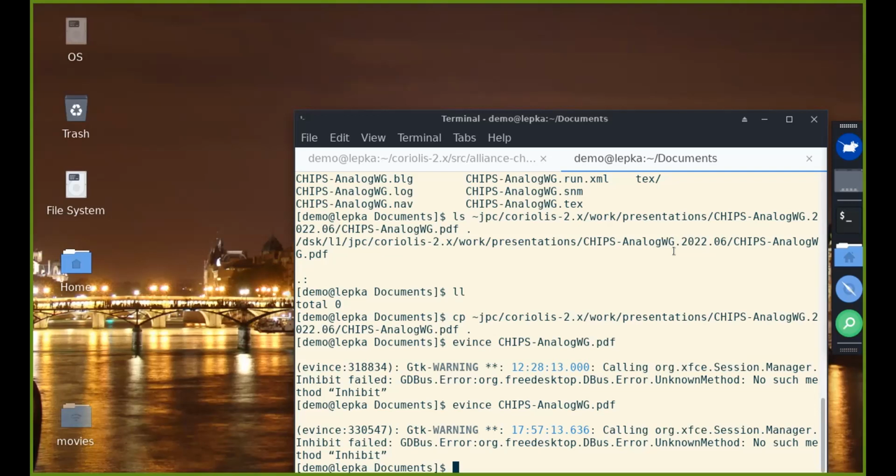As the global router and the detailed router are very fast, it's easy to run them and just extract the wire length. So you can have that quite quickly. I don't mean an extraction. I just mean running the placer and router, and the router in that case, even only the global router, because the detailed routing will follow very closely the global routing. So you can have quickly an estimate of the wire length.